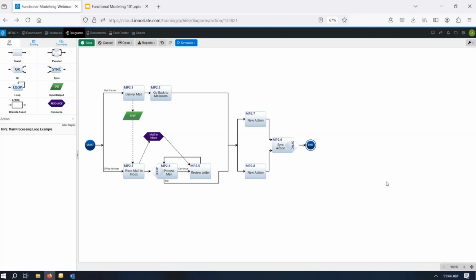What the sync block does is it's kind of the opposite of a parallel structure. In a parallel structure, for me to get to this point here at the end of it, each of these branches must complete. Only when all of the branches are complete can I move on from the parallel structure. So a lot of times when you're doing debug, you'll see yourself get locked up on those parallel structures because maybe 3 out of the 4 branches finish, and the other one's locked up because it's waiting for something it will never get. So with a parallel structure, everything has to finish.